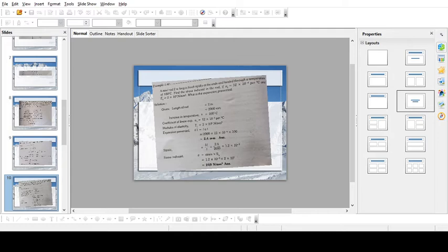The modulus of elasticity is given; you need to find the strain. The change in the length, elongation or shortening, is L alpha T. Delta L is equal to L alpha T, so that is equal to 2000 into 12 into 10 to the power of minus 6.